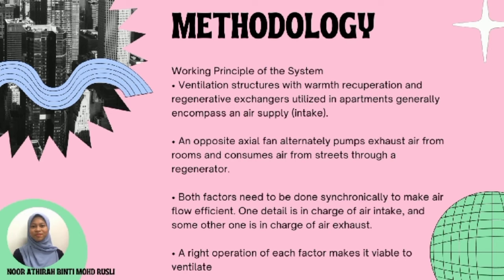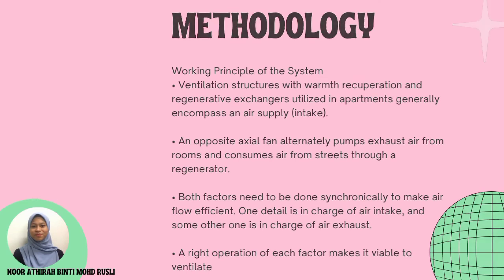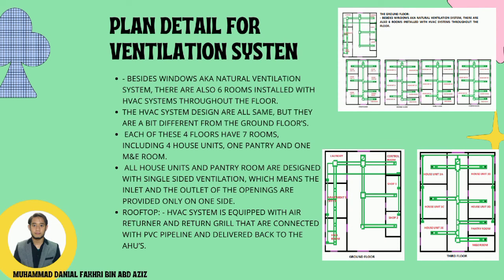An opposite axial fan alternately pumps exhaust air from the room and consumes air from the street through a regenerator. Exhaust air transfers warmth to a thermal conductor. After consumption, air is heated through a regenerator. Both factors need to be done synchronously to make airflow efficient. One fan is in charge of air intake and the other one is in charge of air exhaust. That's all from me. Thank you.